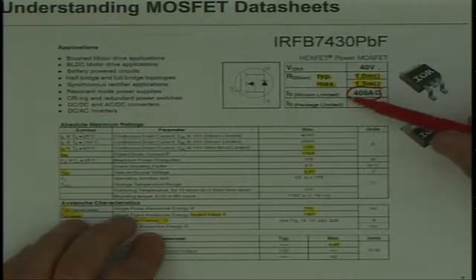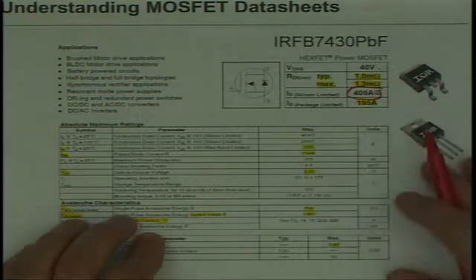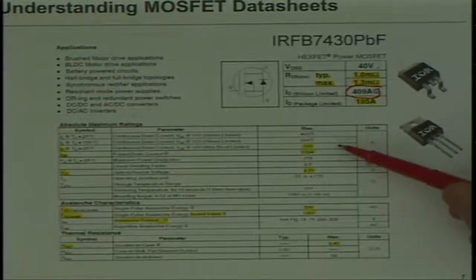It's not real. What it says is how much current the silicon could carry if you could actually get that current through it, and it was temperature limited, and you had an ideal heat sink, like all these what ifs. So it's really kind of a useless number.